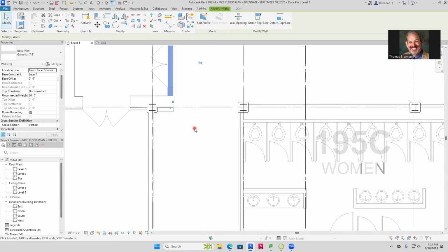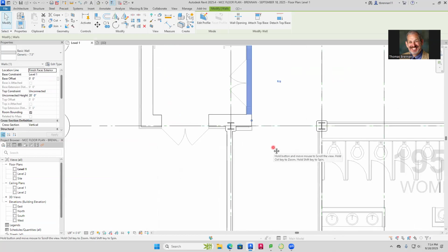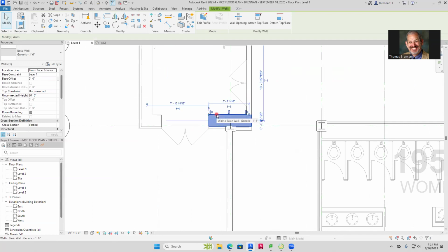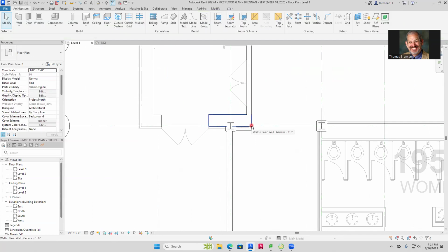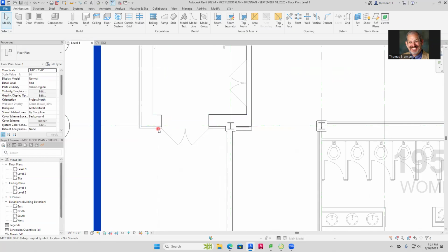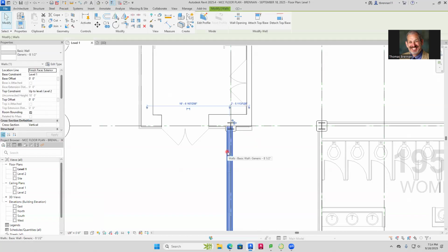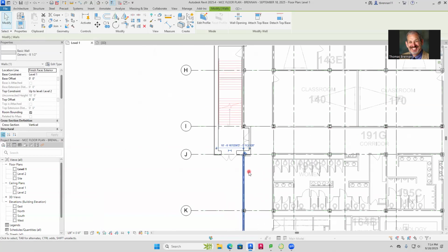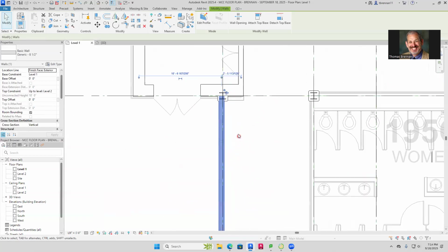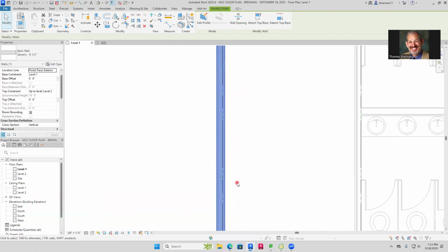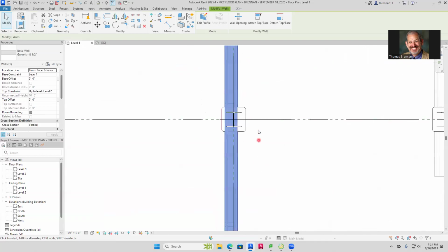So do I put that 8-inch wall through the column? Yep. What I did is I did a 1'6" column, and I just went from this outside, because there's an outside wall right here. And this little bit right here, I'm just not worrying about it. What about the perpendicular wall now? This one is 8.5 inches, so you just use an 8.5 inch wall. Your columns are not going to go directly through the center. That's just the way the plan is.